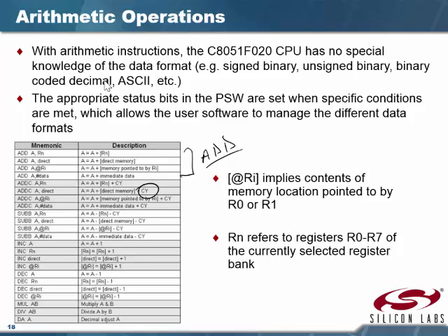But when you add the next 8 bits, you have to include the carry from the previous add. Then when you add the next 8 bits together, you have to include that carry. So it allows you to add a 4-byte number together, and in doing so, you have to carry the flag up there.